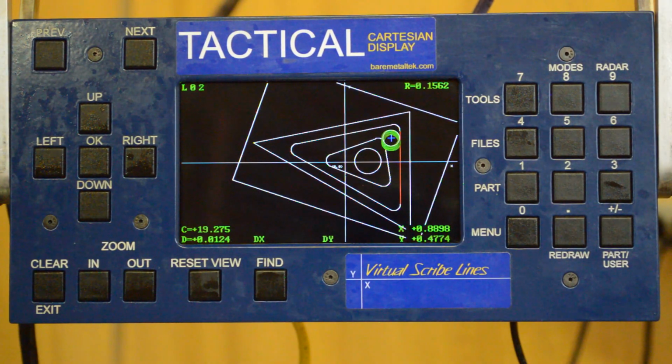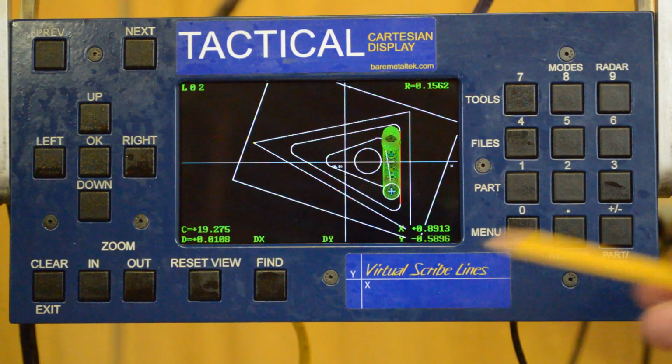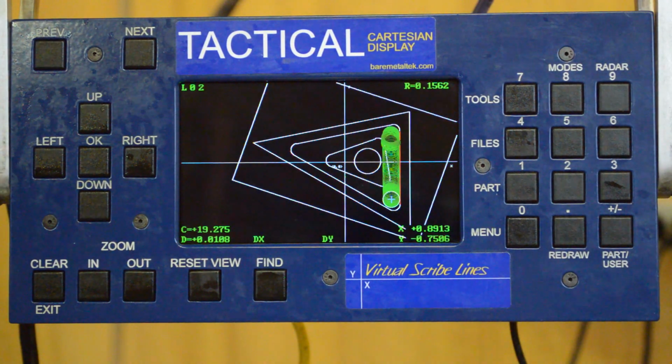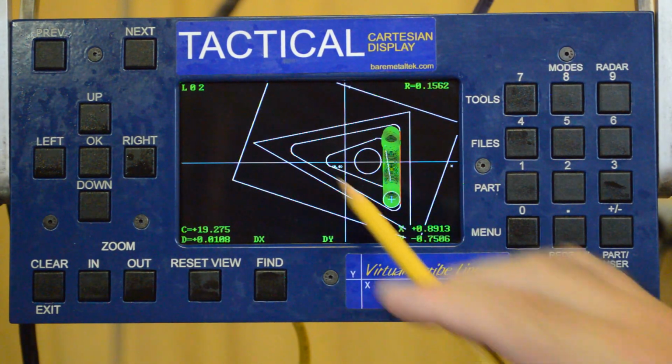All right. And once again, most of the meat is already out of these corners, so I can just back into that corner a little bit, just visually stay away from that line. And I can machine along this wall until I get visually within range of this wall here. Remember, that metal's already gone out of there. So now I've just semi-finished all these walls and all these corners.